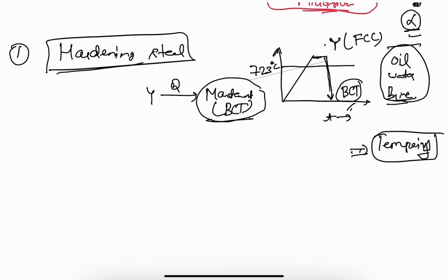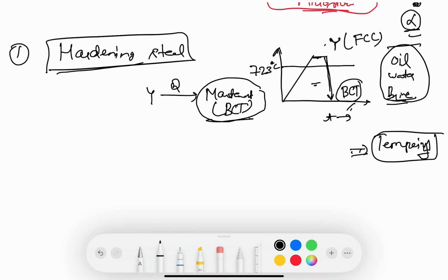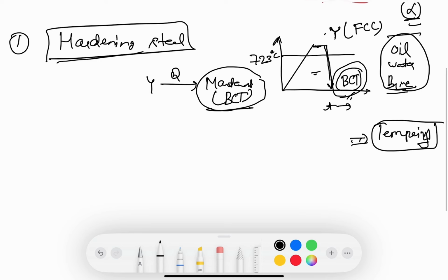Second thing, martensite formation. Martensite is formed during this process. You are not giving time for all the carbon present in the matrix to dissolve out. That's why this body centered tetragonal structure is formed here. All right, so this is the main reason to do this.